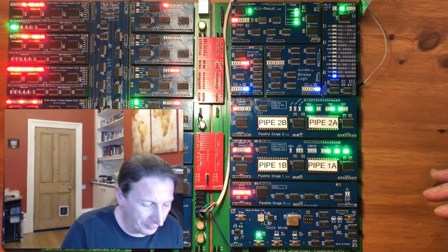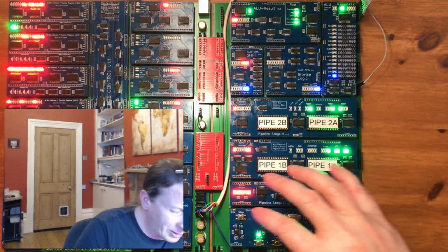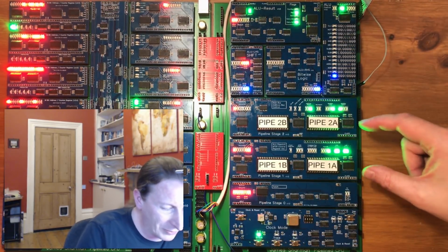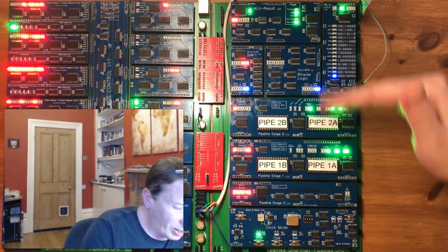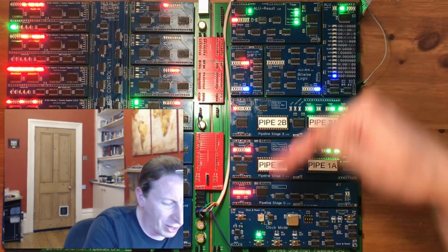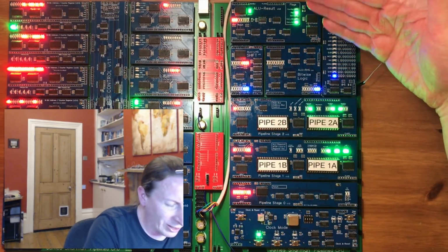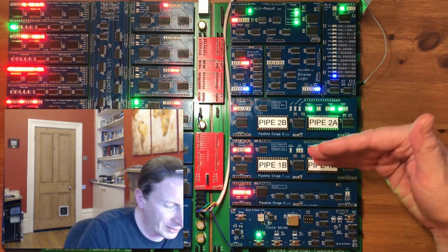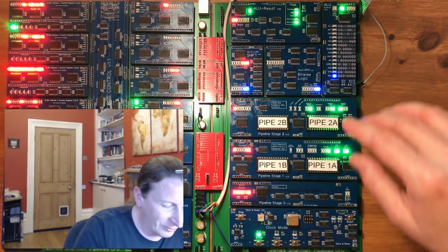I didn't need it. And when I first designed the processor, I was kind of thinking, well, there's some combinations of things here which it might be difficult to cram into 2 steps. But we want the pipeline to be as short as possible while achieving the control goals we've got for the processor. Actually extending the pipeline and making it longer is kind of pointless, because that just increases our instruction latency, the time between starting the instruction and having its operation complete. And I really would have preferred to get away from any of the complexities, such as the value in a register